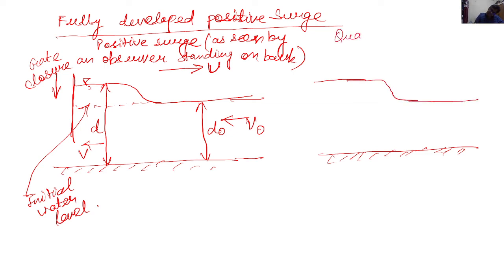So we are trying to make it a quasi steady flow. This is an unsteady flow, but to apply the fundamental continuity equation and the momentum principle, we need to convert it into a quasi steady flow. So this is a quasi steady flow analogy. We just take the control sections towards the corners of the figures to convert it into this. And for this problem, if you are having any issue, then please go through the last question of weekly live session 3 part 2. I have explained it very decently in that YouTube video.